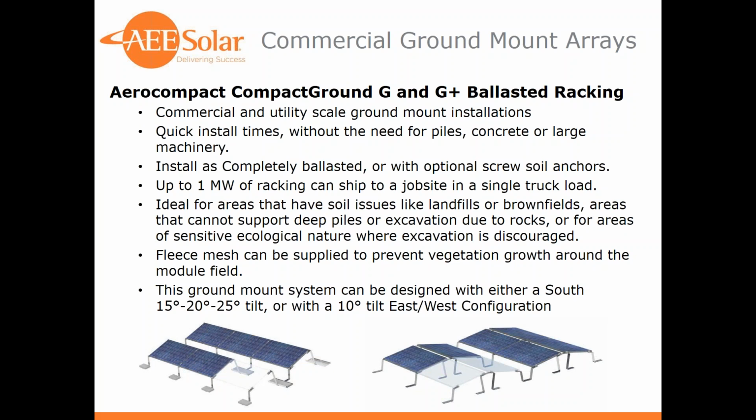Ballasted ground mounts, seeing a lot of interest in this. So if we want to avoid all of the need for digging supports or soil studies, we have the ballasted system here, especially in the lower 48 states. AeroCompact has a 15 and a 20 degree, 25 degree with special ordering, or the 10 degree east-west configuration.